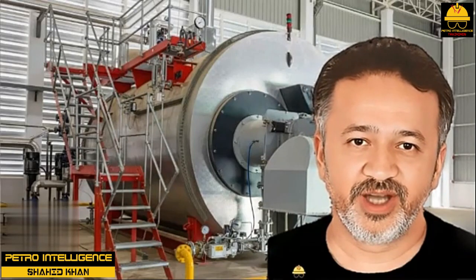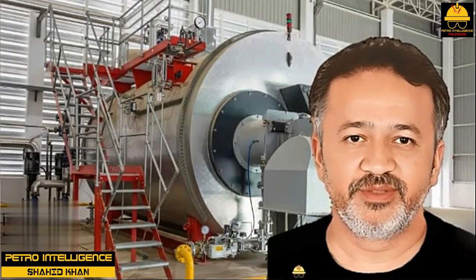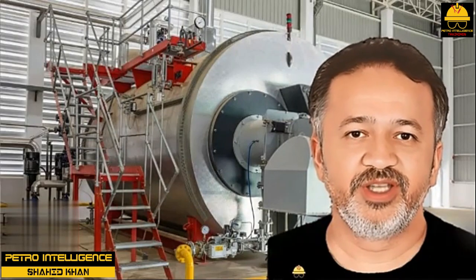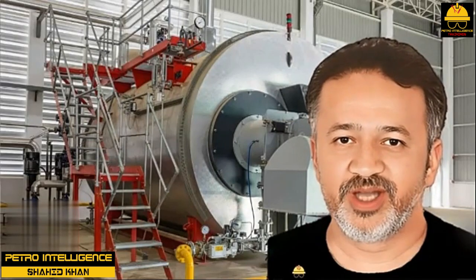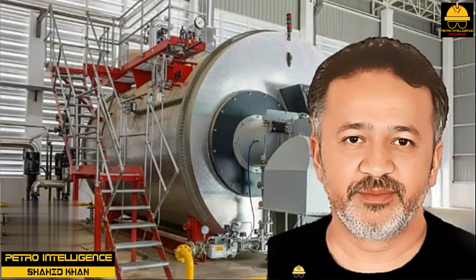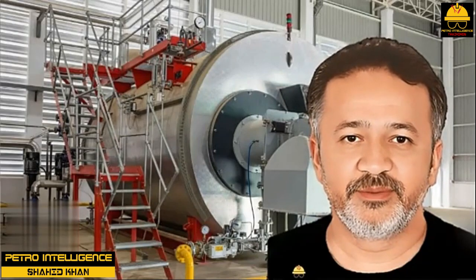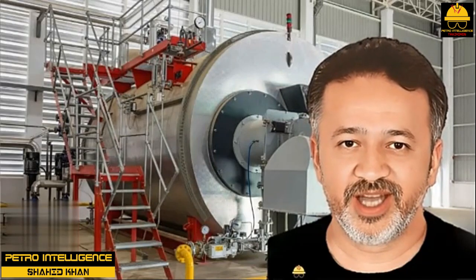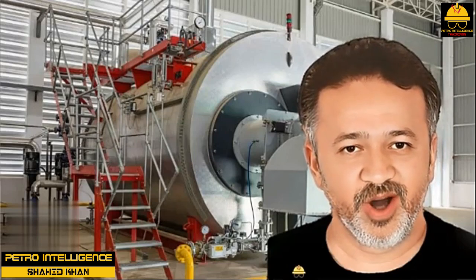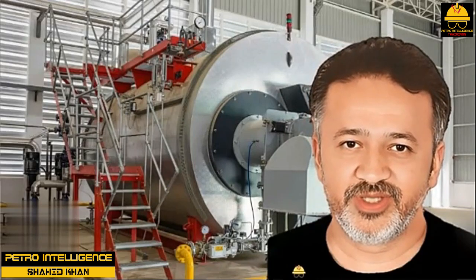This pressure is the vapor pressure of water at the surface condenser outlet temperature. The original steam condensers were barometric condensers, which were used to increase the efficiency of the steam-driven reciprocating beam engines by a factor of 10. Exhaust steam is mixed directly with cold water. As this creates a vacuum, the barometric condenser must be elevated about 30 feet above grade. The mixed condensate and cooling water drains through a pipe called a barometric leg, hence the name barometric condenser.